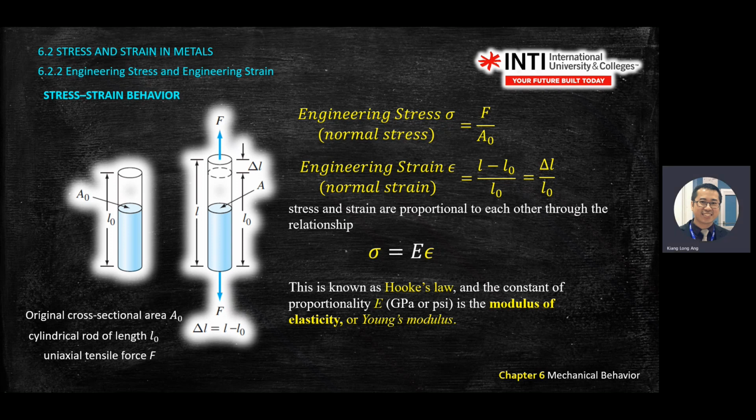Okay, so in your experiment, you are given a specimen, you pull, you measure, you pull, you measure. If you're given a rod like that, you pull, you look at the gauge, how many Newton, then you measure what is the length. You let go. Initial length, you pull, final length, you measure. If you go back to original length, it means it's still within the elastic region.